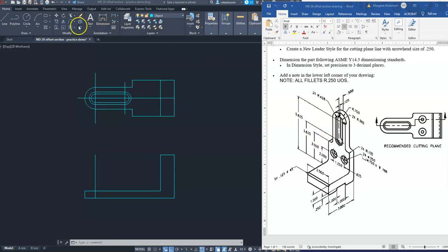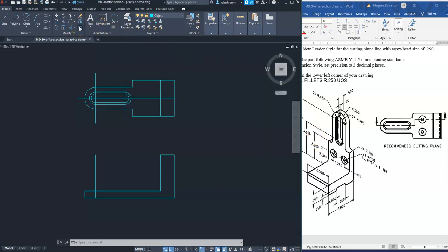So I'm going to get the offset command. Offset, enter a distance of 2, select object, and side to offset. Okay, now they are 5/8 in from one edge and 1 1/4 inches apart.